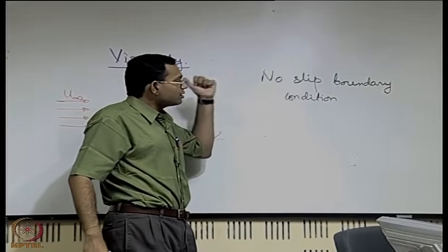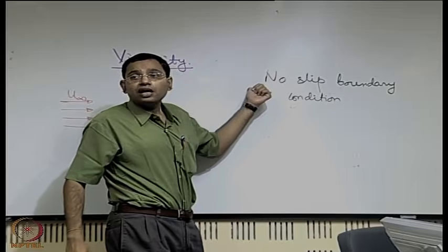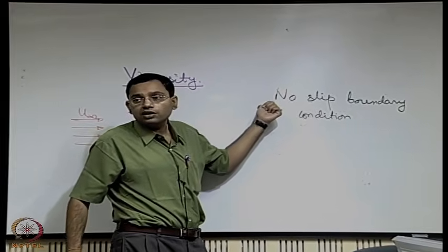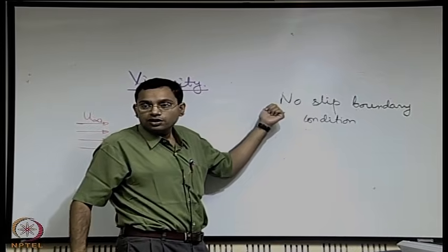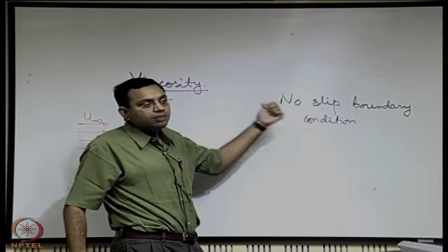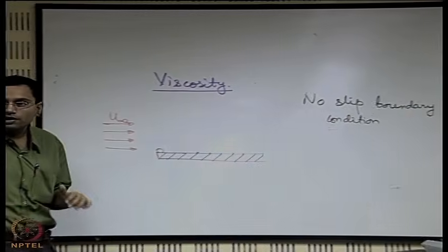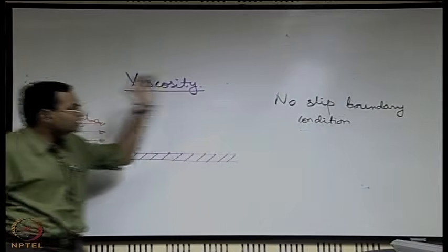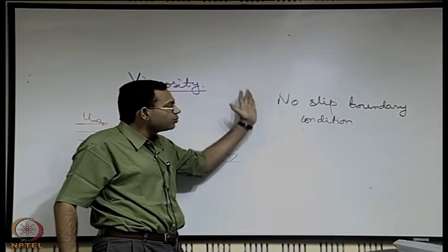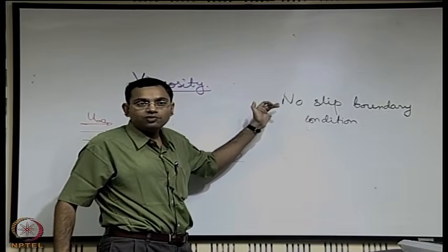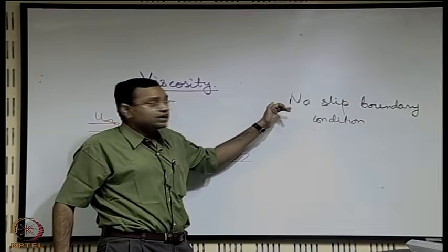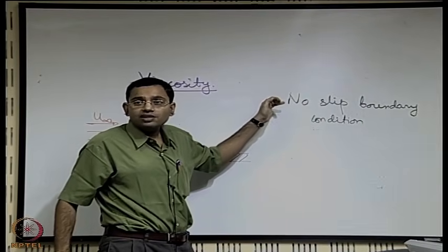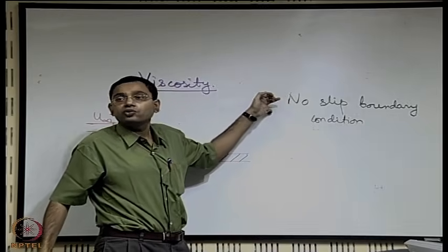But whenever we are understanding this concept, we should ask ourselves a question: are there conditions in which the no slip boundary condition may be violated? It is important because in many modern day applications of fluid mechanics, especially fluid mechanics in small length scales, this boundary condition is put under serious question. So obviously we need to appreciate that this is just a conceptual paradigm. It is not a ritual which is expected to work always.